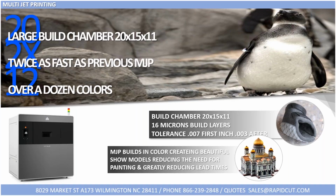Build chamber size, 20 by 15 by 11. But what makes the process unique is it builds in 16 micron build layers versus your typical 4 to 7 thousandths that you see on other machines. This gives it a very, very fine resolution when you're looking at the fine details of your parts. You can do very small features, probably better than any other process.